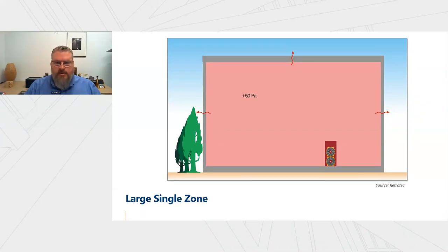That's really what we want to do, and we want to try and make buildings into a single zone if we can, because it simplifies the testing greatly. And by single zone, what I mean is that you're putting the air in at one location, everything is being pressurized at the same time